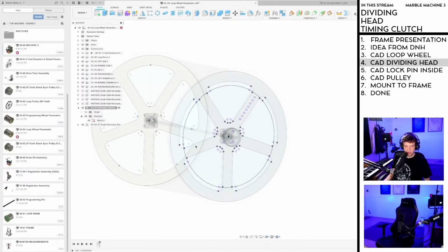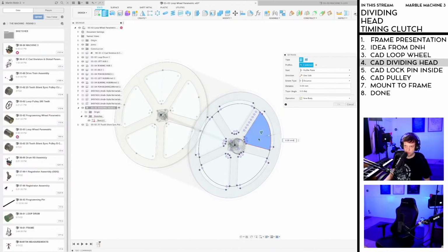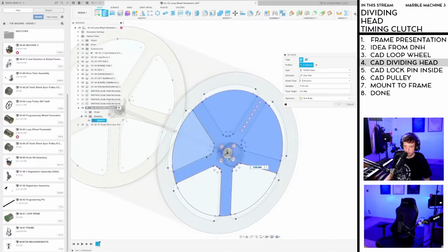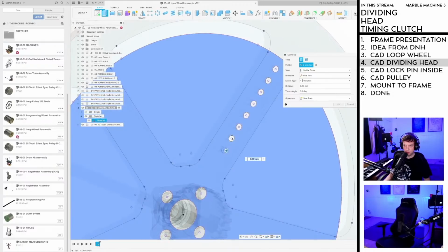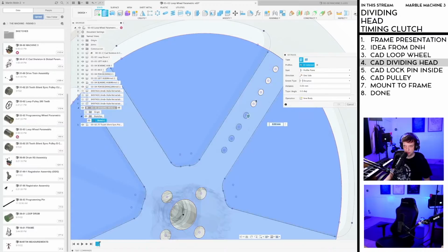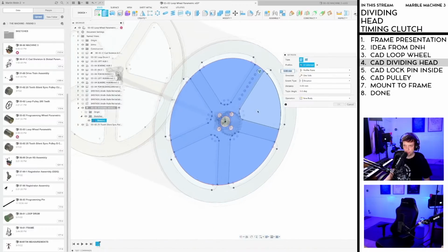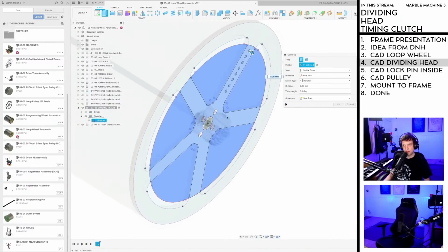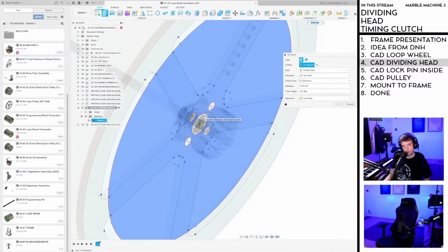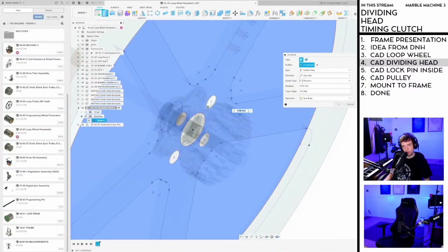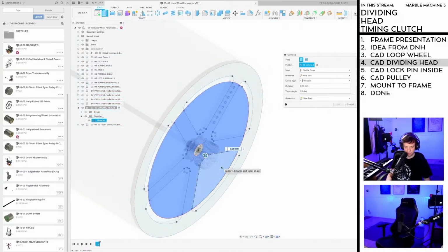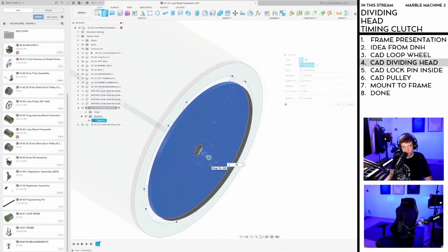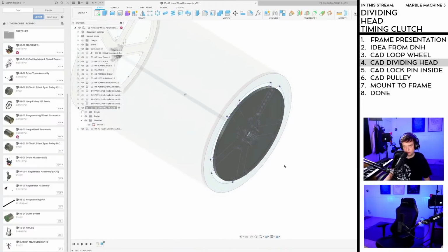So the mistake I did before is that I was using the sketch and I made a circular pattern in the sketch. So now I'm going to make circular patterns with features instead. So that's a good lesson in how to make Fusion 360 just behave so much better. We do not want these 4 holes. Going to cut some holes in this later. So 18mm. There's the disk.